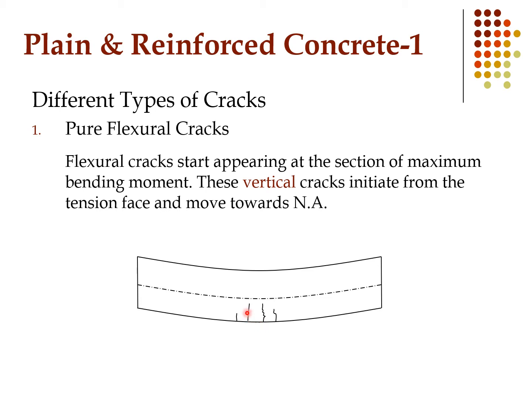So these vertical cracks are actually initiated from the tension face and move towards the neutral axis. You can see that if this is the compression face and this is the tension face, these cracks propagate from the tension face and move vertically towards the neutral axis.